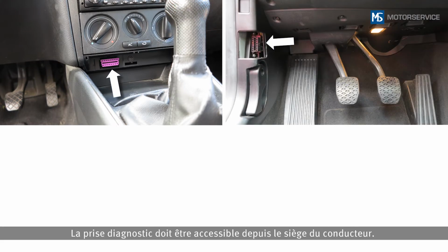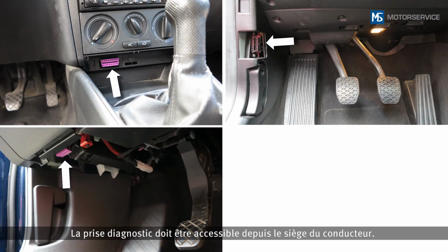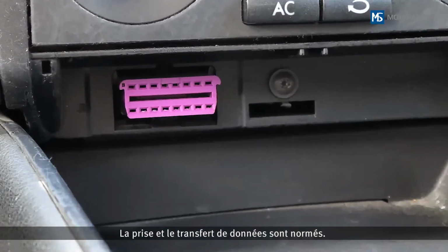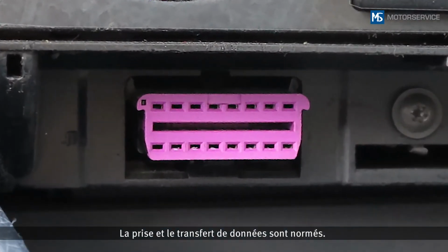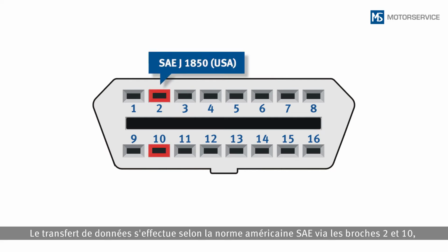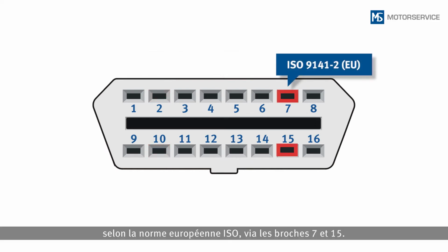The diagnostic connection must be accessible from the driver's seat. The connection and data transfer are standardized. This means that the plug assignment and transfer protocol are the same in all vehicles. Pins 2 and 10 are used for data transfer according to the American SAE standard, whereas pins 7 and 15 are used for the European ISO standard.